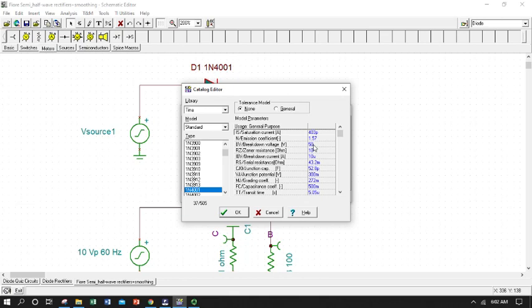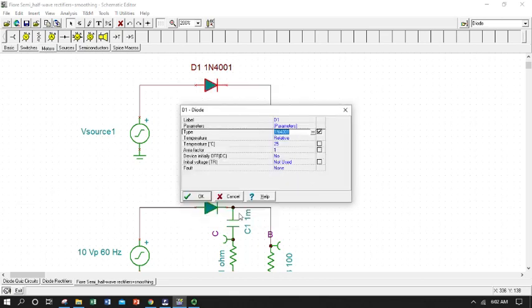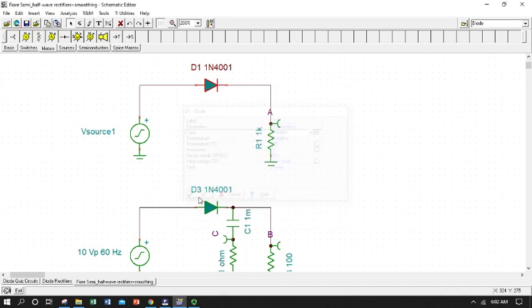If I read my diode specs, I would have known for darn sure that I shouldn't apply more than 50 volts in the reverse bias, and I applied 120. So this is an example of our simulation actually modeling a circuit component failing. I just melted my diode effectively. So basically this is an example of something you would see in a failure scenario, a troubleshooting.